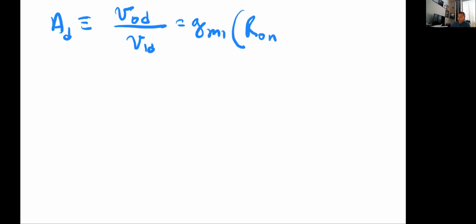So we can write the differential gain for the cascode case at the output node, for 1/2 of the circuit, is going to be the output resistance that you see going down into the N-channel network, in parallel with the output resistance that you see going up into the P-channel network, with reference to the GM of the transistor 1, which is actually doing the amplification.